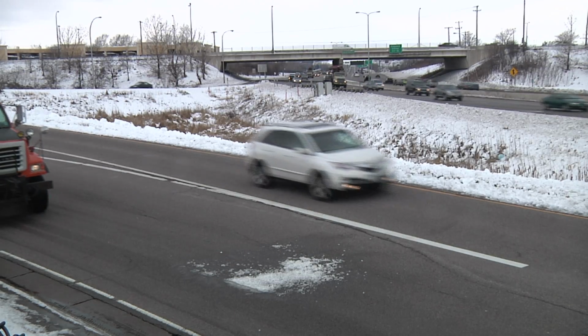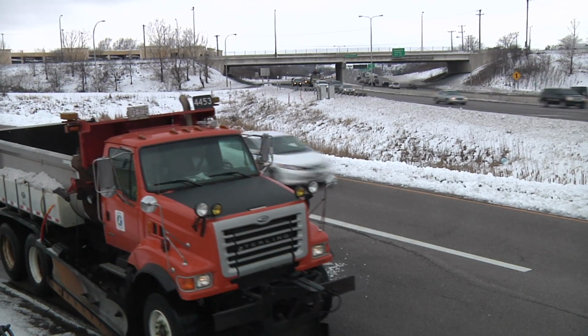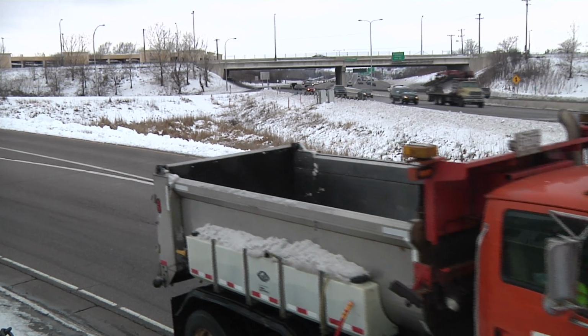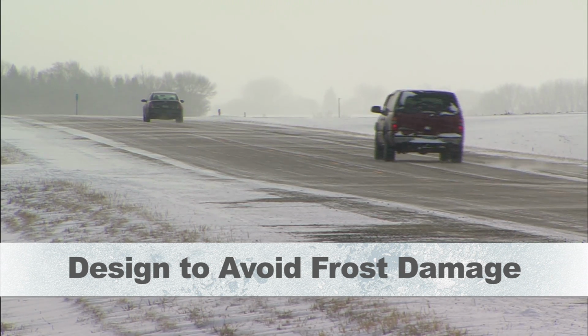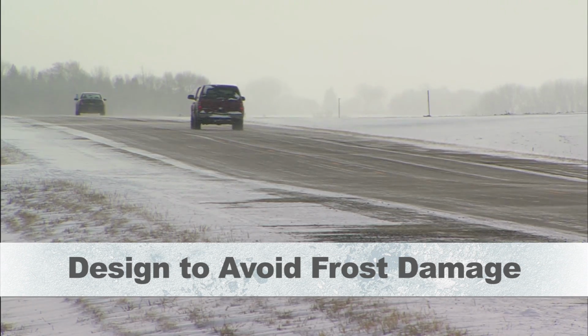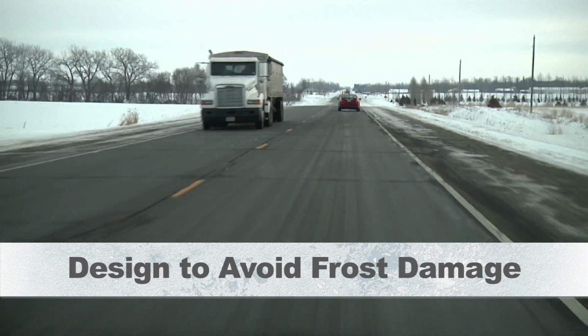There are several effective methods for repairing frost-damaged pavements, or, better yet, for building new pavements to avoid frost damage in the first place. In all these methods, the key is to control the water. If water can be drained out of a material, prevented from entering the material, or prevented from freezing, that material will not be susceptible to frost action. These design methods fall into 4 categories.